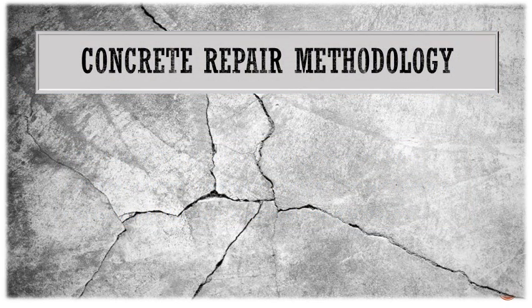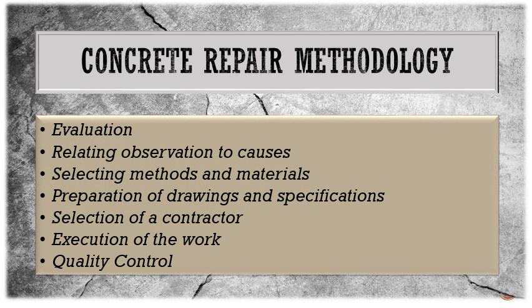The next topic is concrete repair methodology. Concrete repair methodology has 7 steps. First is evaluation, next is relating observation to causes, then selecting methods and materials, next is preparation of drawings and specifications, next is selection of contractor, next is execution of the work, and the last is quality control.